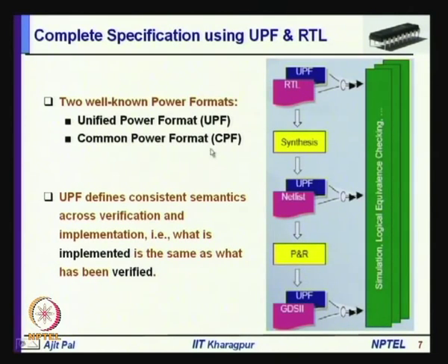So, this is actually not only UPF, there are two well known power formats. One is UPF, that is your unified power format, developed by Accellera, and it has been accepted by many standards. Another is common power format, because unified power format or UPF is most popular. I shall be primarily discussing based on UPF. And as you can see, UPF defines consistent semantics across verification and implementation, and that means what is implemented is the same as that of verified.